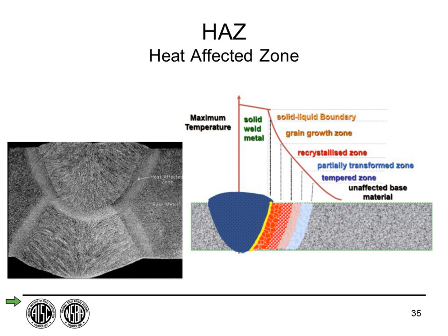It just shows a close-up of a two-pass weld to show you the heat affected zone. The first weld pass is right here. The second weld pass was put on here. What you see is this shaded area. This is the fusion line right here. This is the heat affected zone. What's really critical is this region right here, the coarser region. You'll also see there's a heat affected zone in the weld pass that we welded on top of, and this actually can improve the toughness of the weld. But we're interested in this behavior.